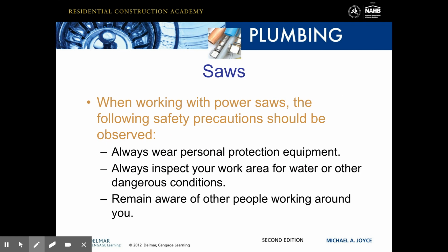When working with power saws, the following safety precautions should be observed. Always wear PPE, and again here, that's muffs, proper uniform, safety glasses. Always inspect your work area for water or other dangerous conditions such as debris, sawdust, grease, oil, anything like that. And always remain aware of other people working around you.